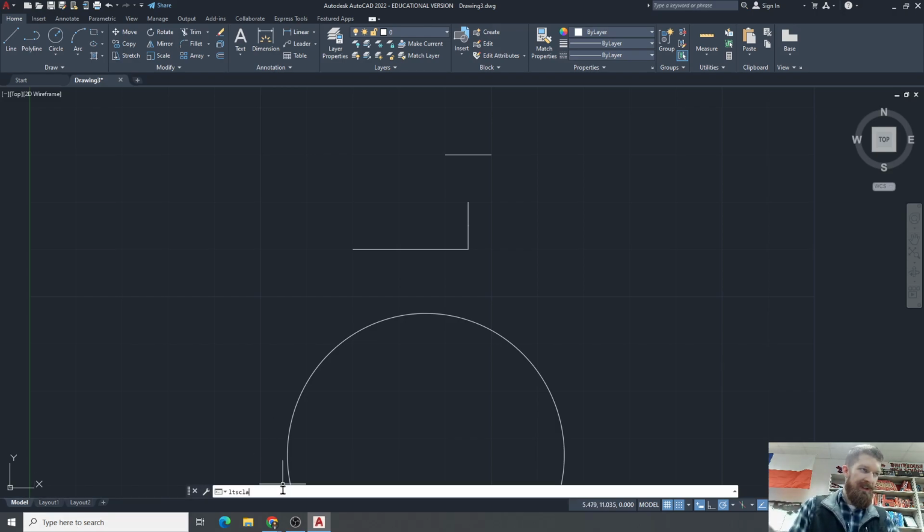So LT scale, right? You can change that. Default is 1. And then if we were going to use one layout, we would say PS LT scale is 0. And we can go over that more in class. Just get with me if you've got questions on that.